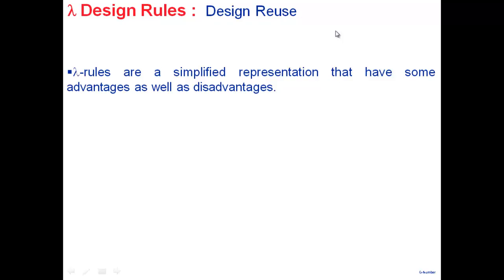Now, remembering that something is 180 nanometer, another thing is 200 nanometer, something else is 350 nanometer, is hard, right? So specifying everything in terms of 1 lambda has several advantages. First of all, it's easy to understand what the rules are in terms of 1 parameter, lambda, and the rules are all integer values, 2 lambda, 3 lambda, 4 lambda, which is easier.